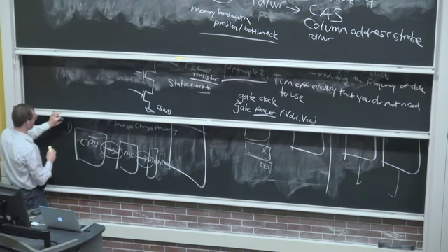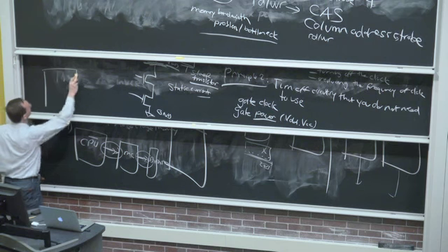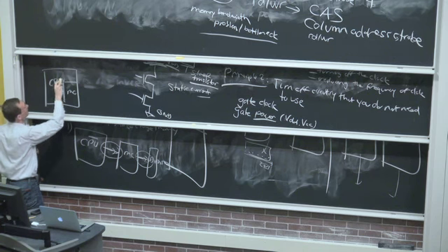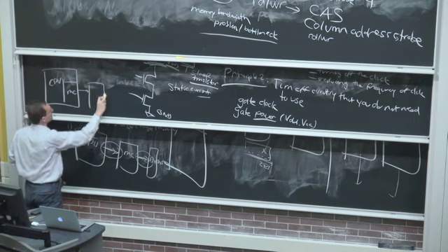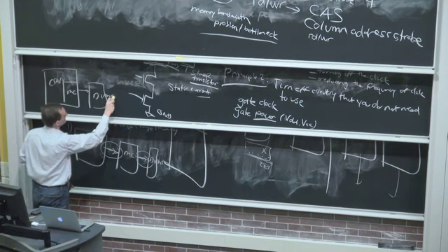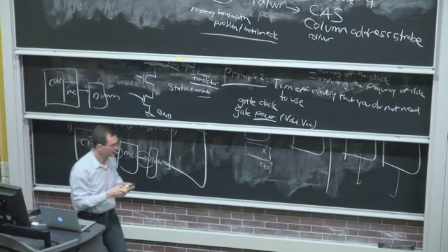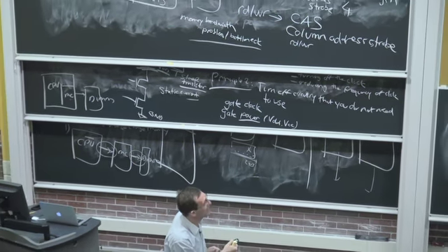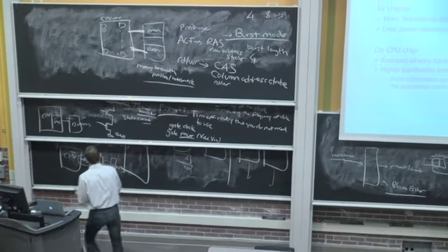I guess option 2 we can do here. CPU, and you have the memory controller on the CPU. This is the second option, and it connects directly to the DIMMs. The memory controller is integrated on the same chip as the CPU. That way, you get reduced latency, and you get higher bandwidth between the cores and the controller, right?